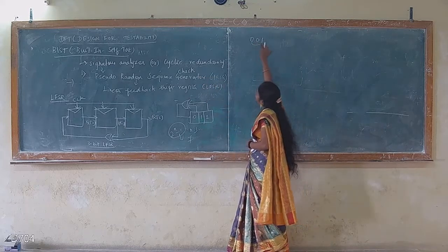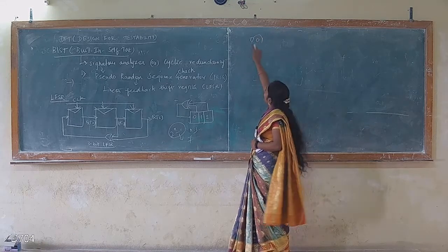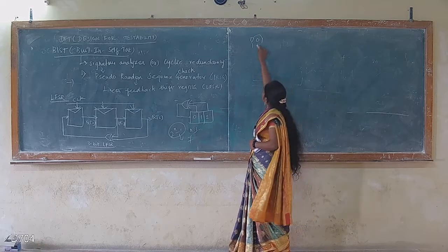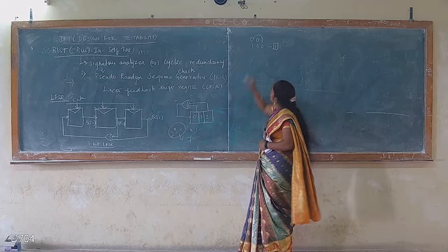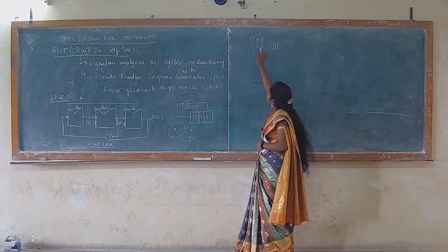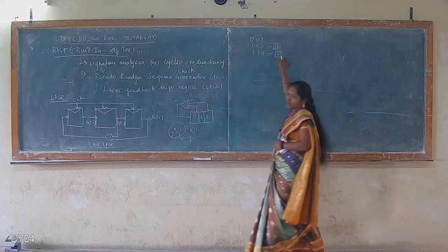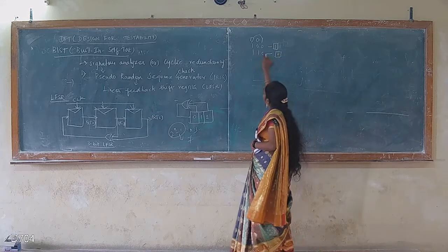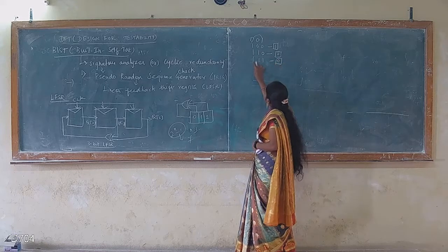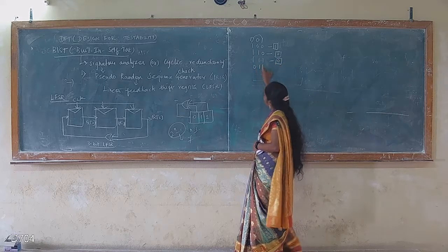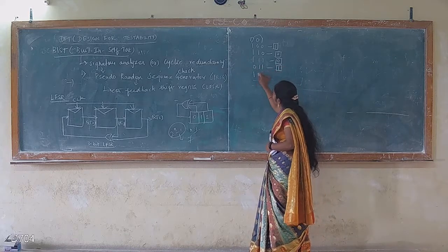First we have to do the XOR operation for 0 and 1, so it is 1, and we do the 1-bit shift. So it is 1, 0, 0. Then taking 1 out, again 1 XOR 0 is 1. Then shifting, we are generating the pseudo random sequence, and again 1, 0, 1. Then 1, 1: XOR is 0. Then 1, 1, 1. Then 0, 1, 1.